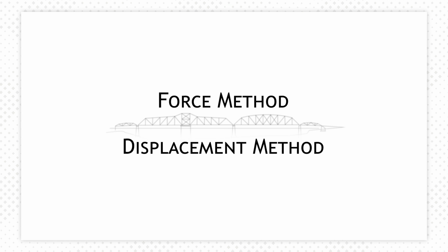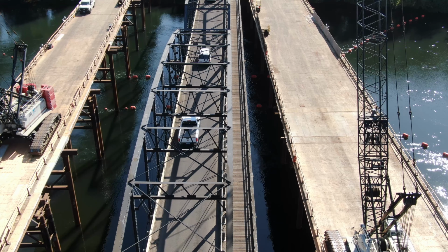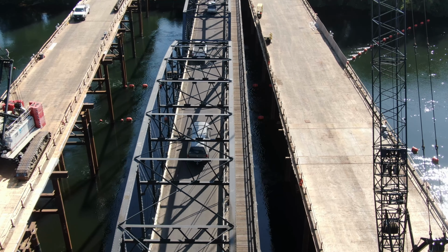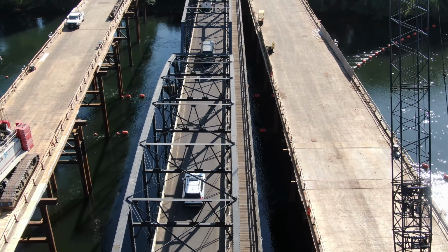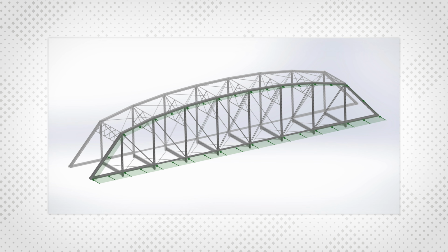There are two fundamental seismic design methods for bridges: force and displacement. They both use seismic force, which we will discuss here. In the force-based method, we apply calculated lateral forces on the bridge and evaluate their effect. We allow some elements to yield and keep other elements elastic. This design force is applied to the structure as a distributed horizontal line load. In its simplest form, this load can be used to evaluate the resulting member forces in the super and substructures.